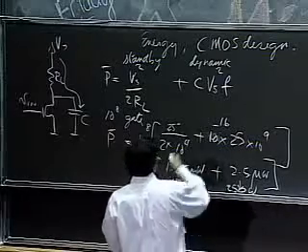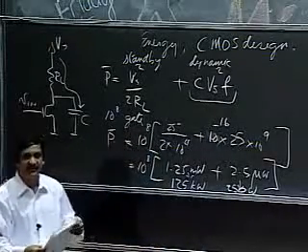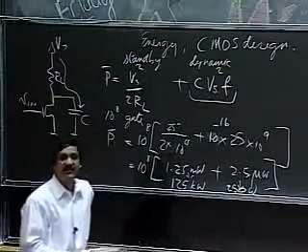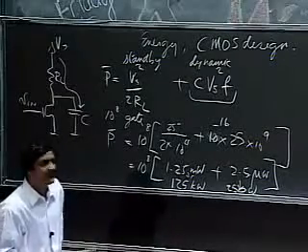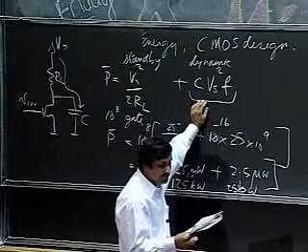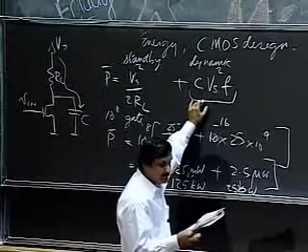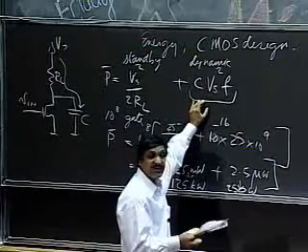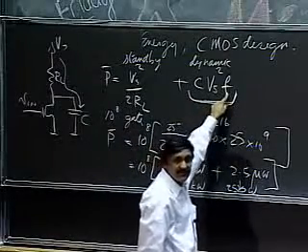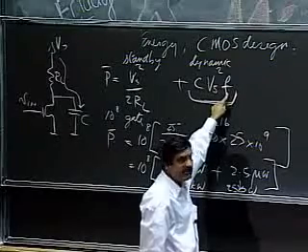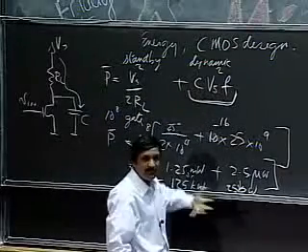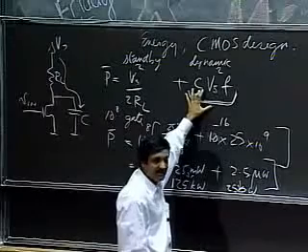Also, I want to dwell for a moment on this term. If you look at the spec sheet for the IBM ASIC process that we handed out, it talked about power dissipation of 0.006 microwatts per megahertz per gate. Now you see where it is coming from. Per megahertz, because the power is a multiple of F. Second, it's per gate, so this is the power per gate. As I have more gates, I just have that much more power dissipation.